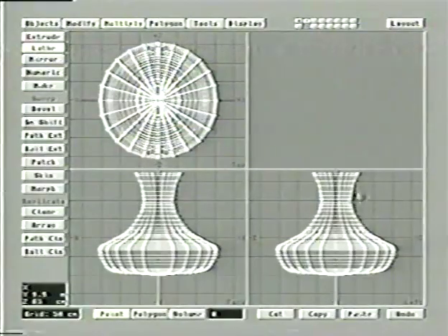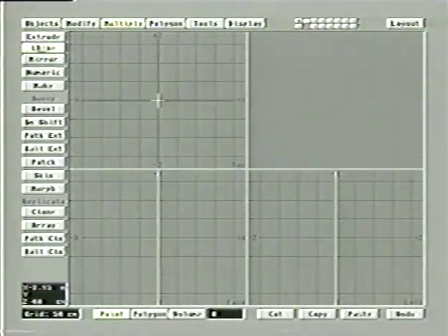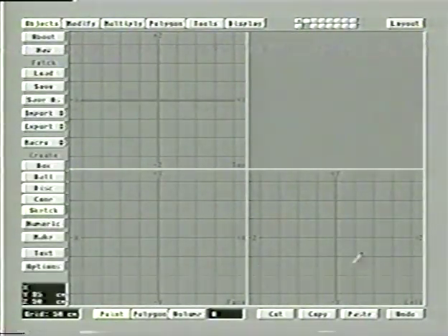There's a problem with the urn that we've created here, though, and that's that it has no depth whatsoever. Because I just drew it as a flat thing, it literally has no depth. Now, I could get around that by using the double-sided option, so we see both the inside and the outside from the Surfaces menu. There's another way to do it, though, and that's to actually draw an inside and an outside. And let me show you how we do that.